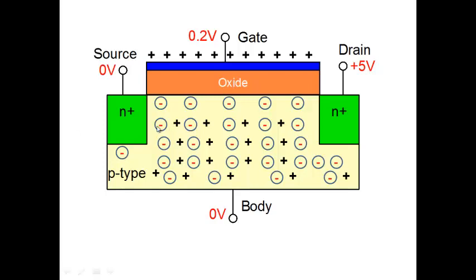Right? Now, originally this particular layer had which carriers? Holes. And it had very few electrons anyway. And now you have removed the holes also from the surface here. So this layer is depleted of carriers. So I have a depletion region here. I'm drawing a dotted line showing that there's a depletion region.